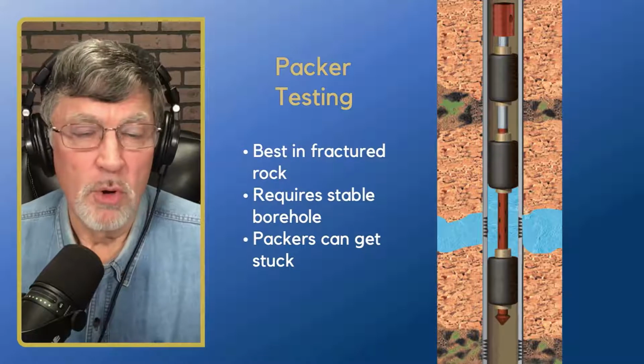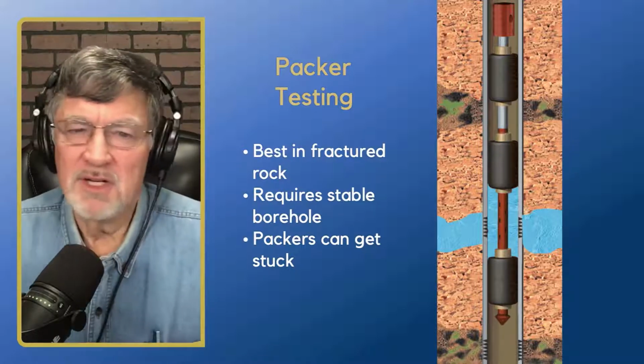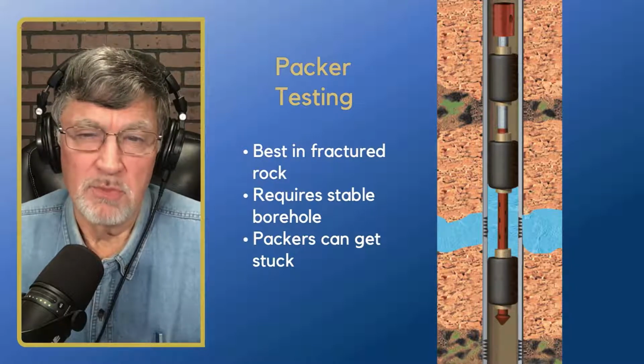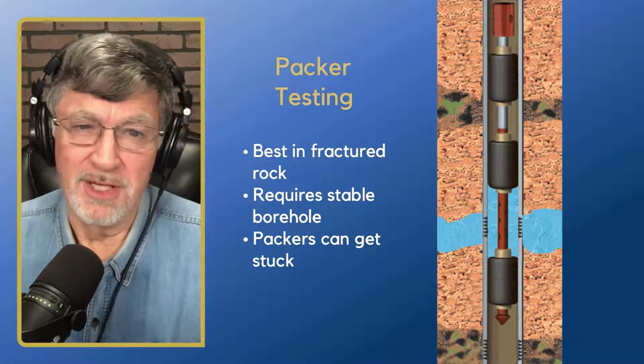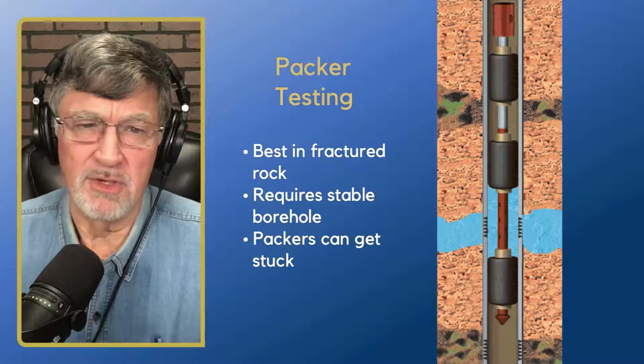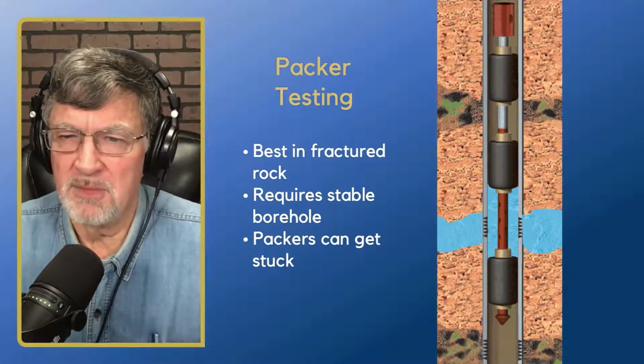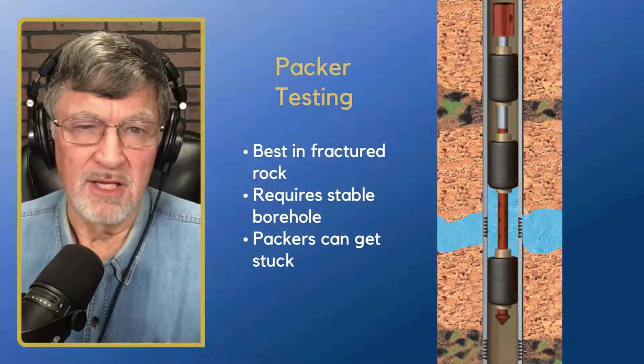Requires a stable borehole. So oftentimes not good if you're in an alluvial well. And we have had incidences where packers can get stuck in the hole, and then you do a bunch of damage trying to get them out. So there's no guarantee they're going to go in and out very, very smoothly. Sometimes they just don't deflate like you expect them to do.